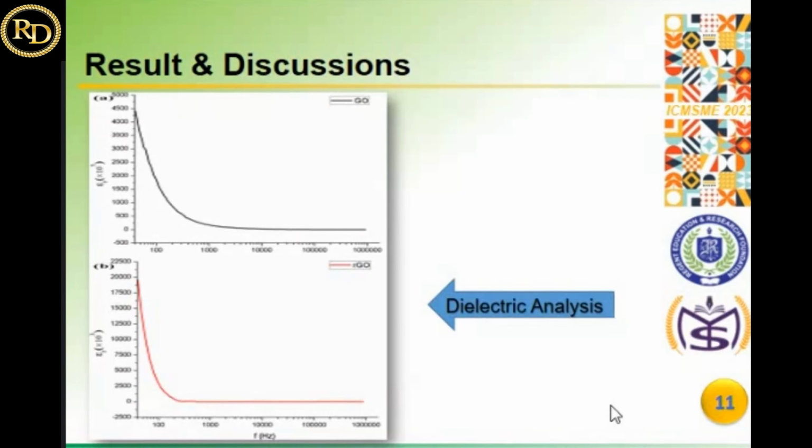We can see that at a lower frequency, around 35 to 40 hertz, graphene oxide attained a dielectric value of around 4.4 × 10^6. But when the frequency was increased to around 1 kilohertz, the dielectric permittivity reduced considerably to 1.7 × 10^5. Likewise for RGO also. So at lower frequency, the dielectric permittivity of the substance that has been created in the lab is considerably higher.